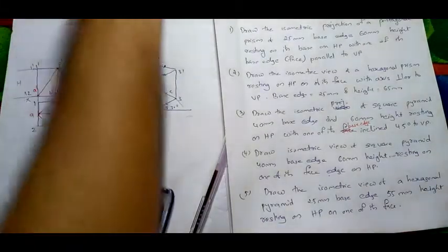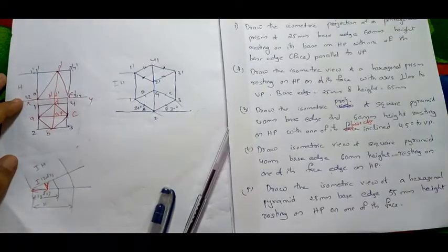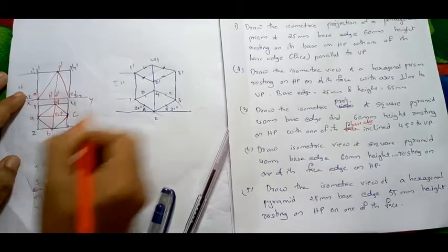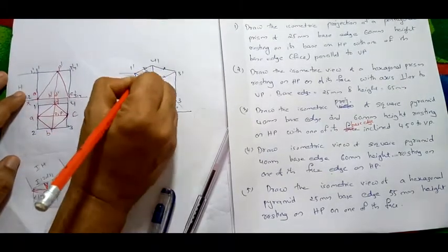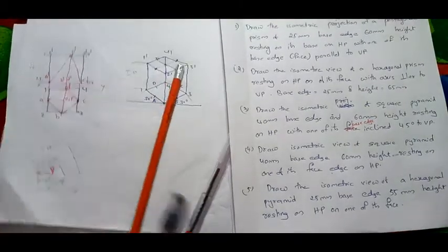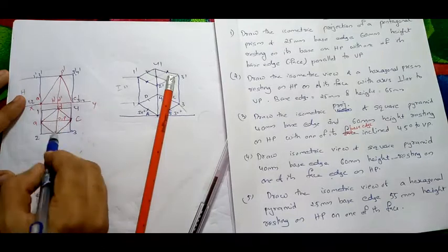Now draw a line similarly from this passing through these points. Now next find these 2 points. Draw a line parallel to C. Now you have obtained P. Never take these lines. These are not isometric lines. See, AC is an isometric line, also BD is an isometric line.